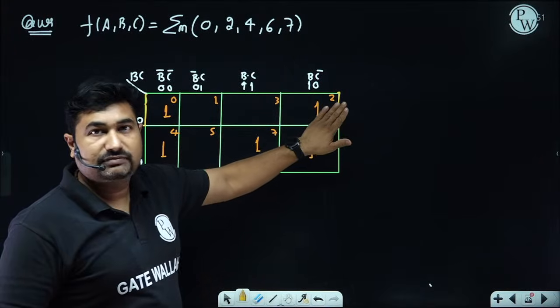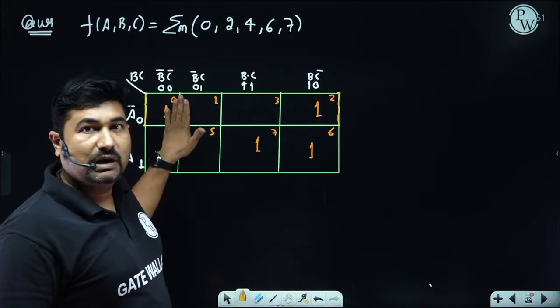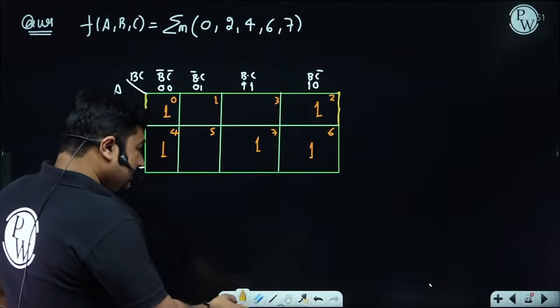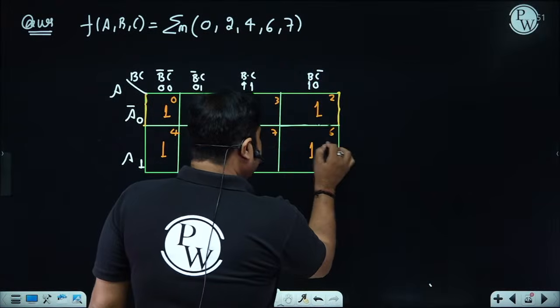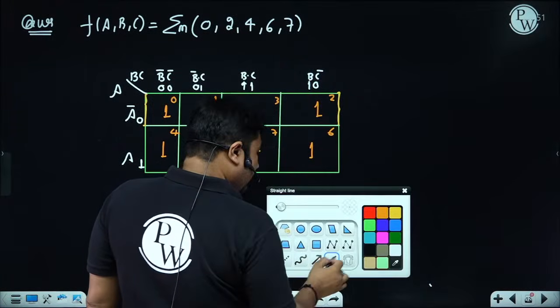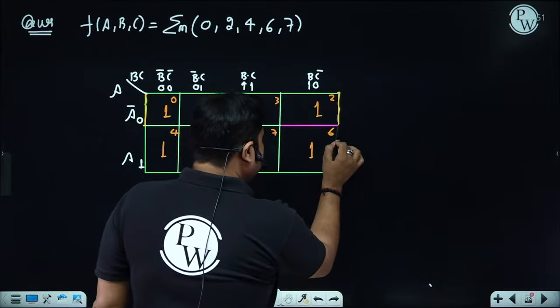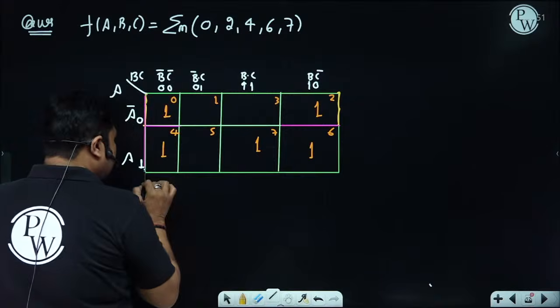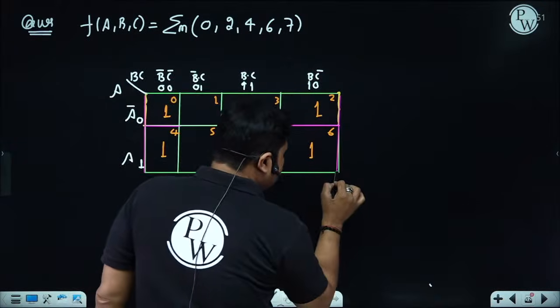So gray code of 3 and gray code of 0 also differ by only 1 bit because it is a cyclic code. So what does it indicate? It indicates these 4 subblocks are also adjacent subblocks. Basically, they are sharing this boundary.